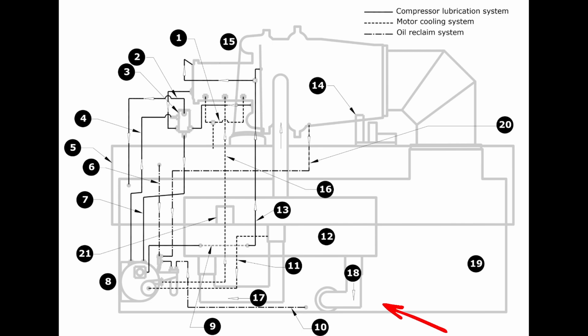And train in the same way, their reference is, for example, I've seen these filters be frozen solid blocks at times, and they'll be really cold. These shouldn't freeze or have excessive sweating on them. And what I find is usually that's because this valve is open too far, and you choke this down a little bit, and these won't do that.